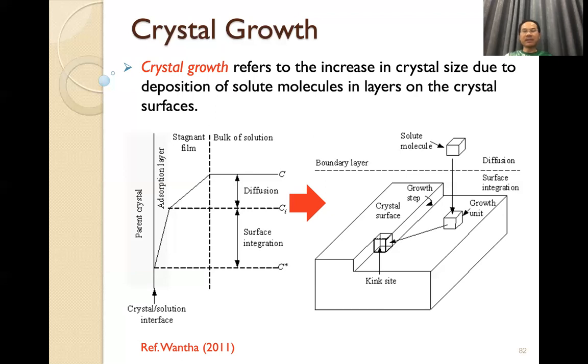Supersaturation we separate into zones. The labile zone is a very high concentration that leads to nucleation. The second zone is the metastable zone, the zone that is close to the solubility or saturation line. For this case, the driving force is not high enough to induce new crystals. But for this case, we can induce the crystallization by crystal growth, right? We have to see the crystal.